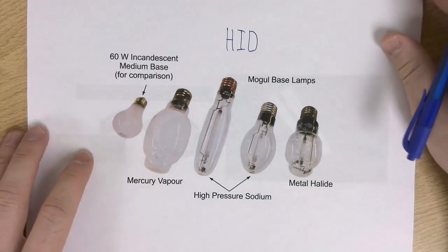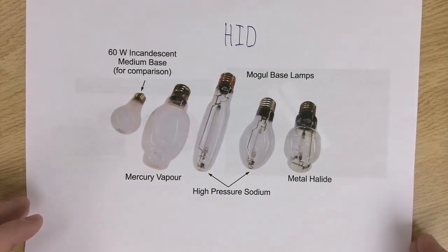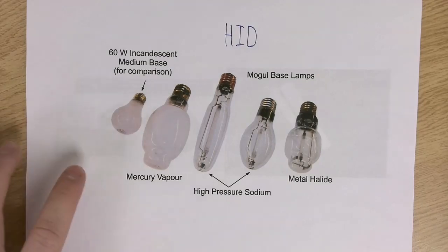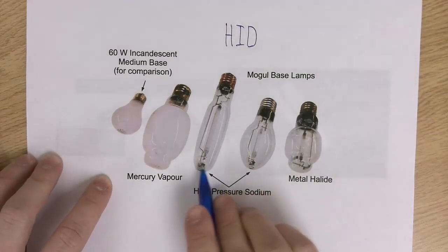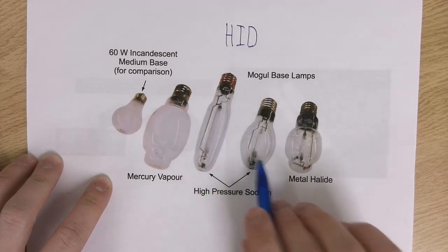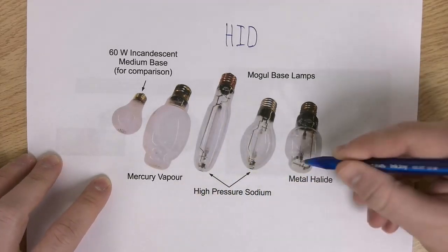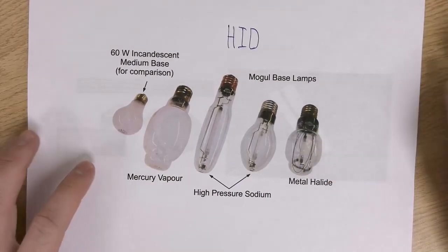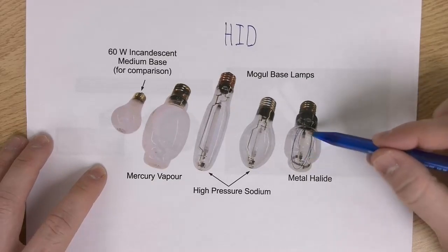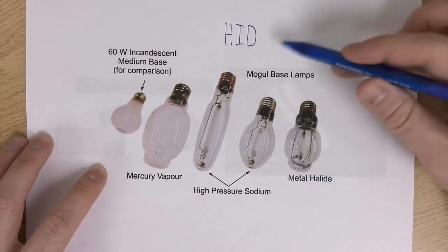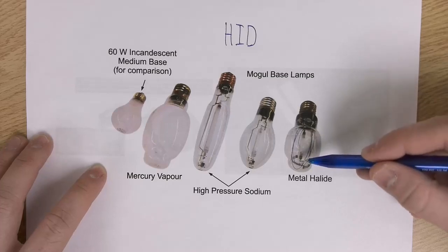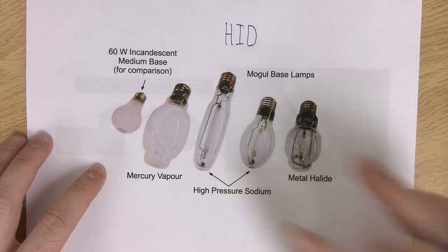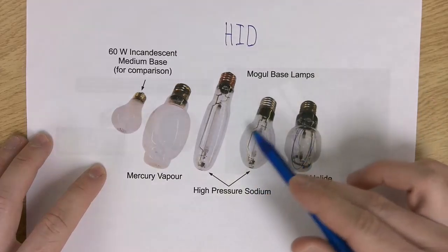And so instead of just a ballast controlling the energy and lighting the gas, as you can see in these clear or transparent glass bulbs, these actually have a large filament that functions as an igniter. This is what it means when it says high intensity discharge. It builds up this large arc, and if you've ever seen one of these bulbs turn on, you will actually see some kind of spark or ignition of the gas.